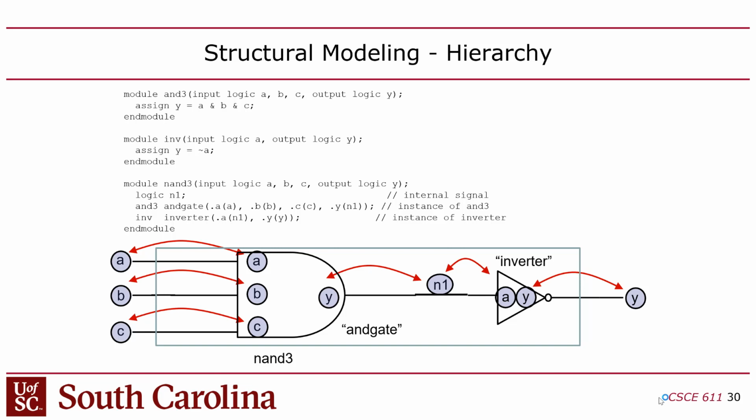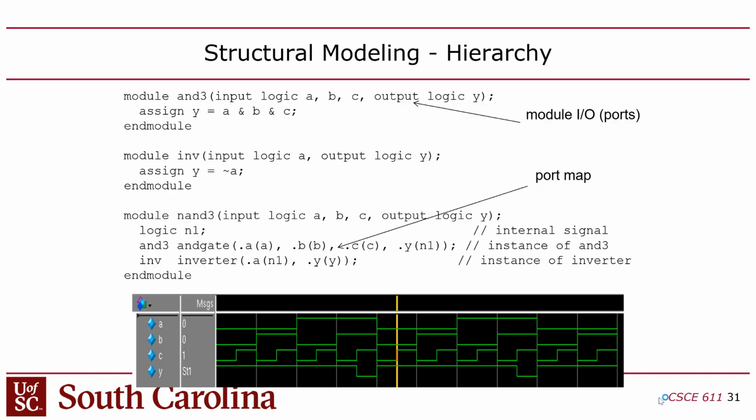You can put in a virtual logic analyzer and read these through JTAG, that's the debugging protocol. But when you go to pick your signals, you have no idea which signal you'll actually see, because when it puts this inside the final design, it only uses one of these names. There's no way to tell which one it's going to use. So sometimes it's hard to track these wires down after you synthesize if you use that style of debugging. We'll be doing that in this class. I'll show you how to do that.